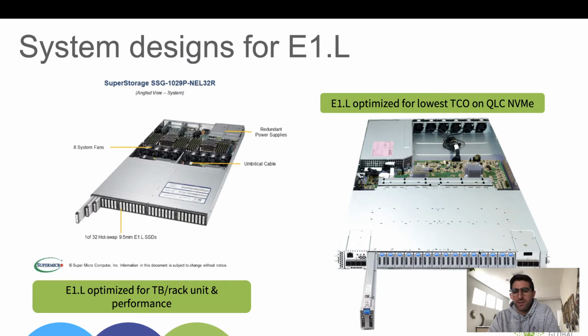This is one of the other OCP inspired designs that you can find on the OCP website. It's a server from WeWin that uses the 18 millimeter version of E1.L. So again, for a standard by 4 SSD that's 25 watts, this is probably a little bit overkill, but it's a little bit better for TCO because you can run the fan speed a little bit lower. As you imagine, an 18 millimeter heatsink versus 9.5 can just dissipate a little bit more power. But we don't expect this one to be mainstream going forward. I think we are seeing most of the interest in this kind of 25 watt E1.L around 9.5 going forward. But the spec does call out both of these, and certainly whatever designs are interesting.